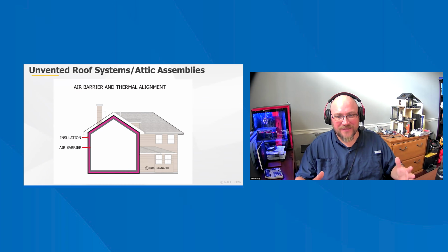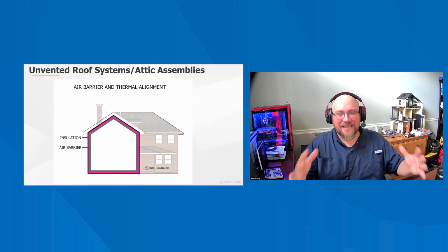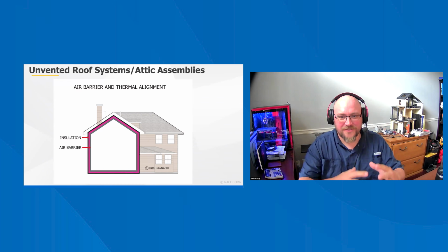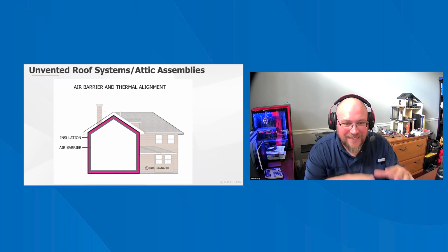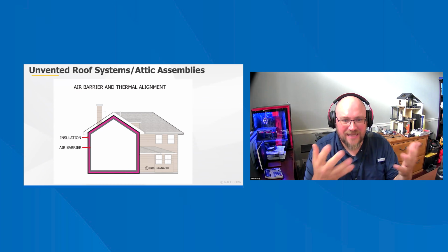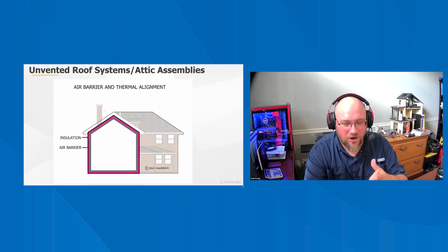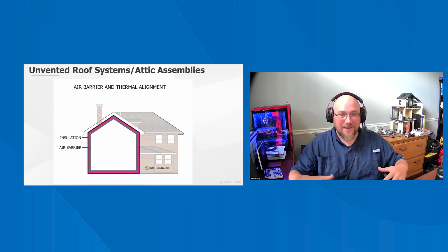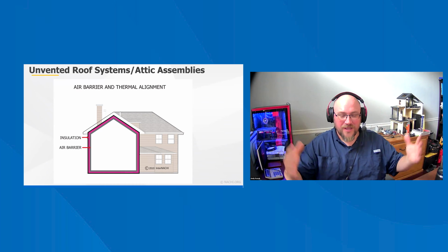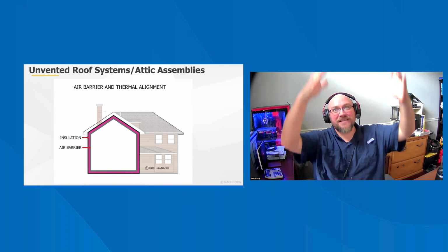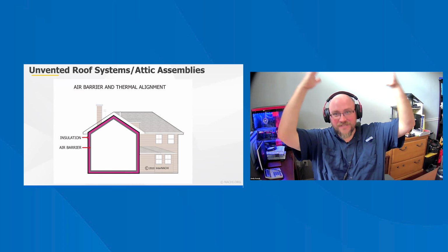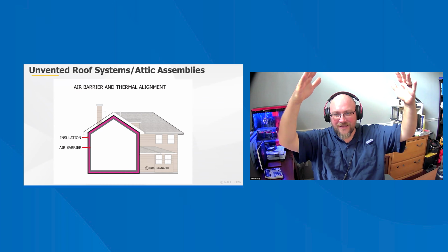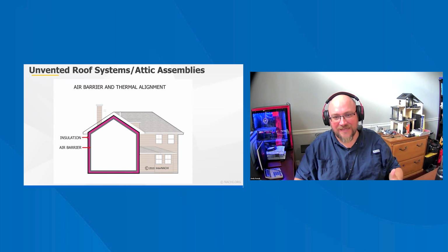So basically, when they put the new roof on, they basically put a hat on top of their house, and any moisture that was produced inside of the house, either from just RH, relative humidity, when it had rained inside, or whether they were cooking inside, or showering, or whatever they were doing, that moisture had nowhere to go. So it was rising up to the roof ceiling, it was condensing on that roof plane, and it basically rained inside of their home.